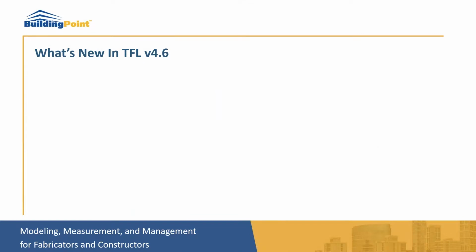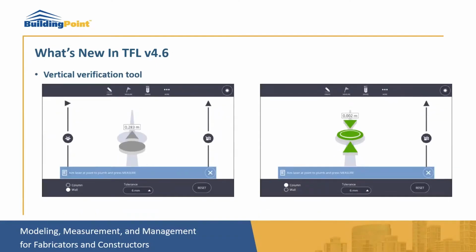In the latest and current version 4.6 of TFL, this really, really cool vertical verification tool was made available. So it's a super easy command to use. You don't even need to do a station setup to be able to use this command. You just need to set your instrument on a tripod, level it, connect the tablet to your instrument, and the function or the tool will already be available.